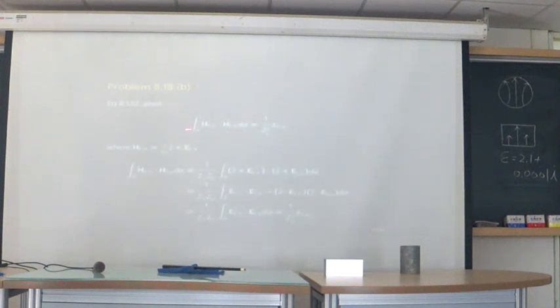So for equation 8.132, we have the integration of the H fields' inner product. You can change the H field by the definition, H is equal to z cross ET, and change the integration of the H field inner product to the integration of the E fields' inner product. And then use equation 8.131. You can find that it is basically the same, but just up to an impedance constant here.